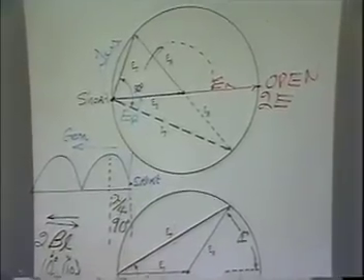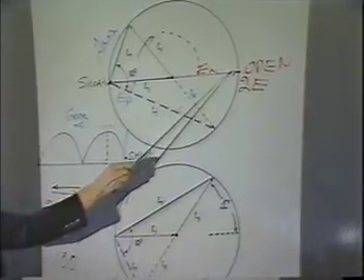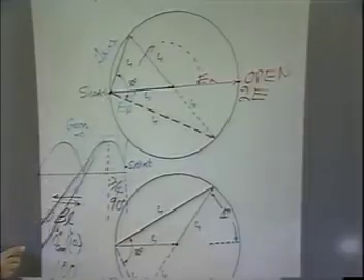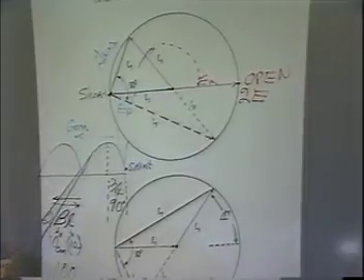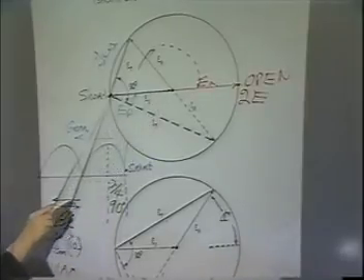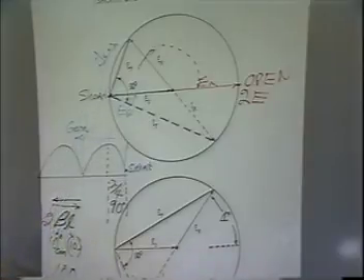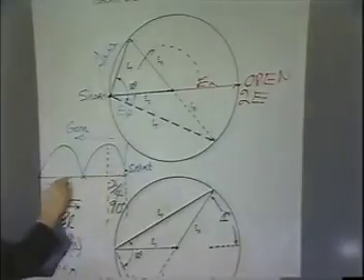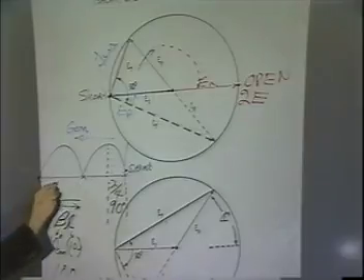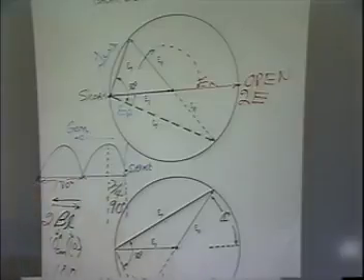That holds, doesn't it? What happens now if I take E sub R and rotate it all around here, back over to here? In other words, I travel from here back along this line to E minimum. I've traveled back to the point where these two cancel. I'm back to the short circuit again, right? So every 180 degrees, I have this, this, this. The distance from here to here is 180 degrees, and from here to here is 180 degrees. So 180 plus 180 tells you that that is one wavelength on the transmission line.